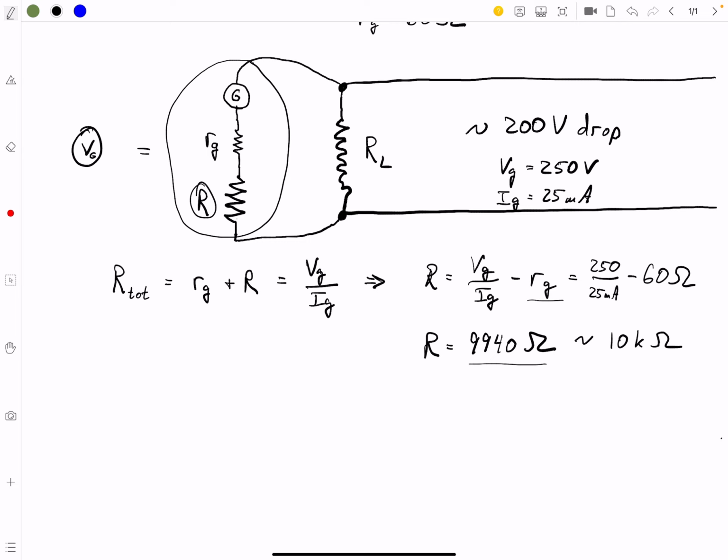So this is the resistance that we have to have in that, when we select that 250 milliamp selection, we are selecting this resistance inside as a shunt resistance. And all of that ends up giving us a 6.67 ohm shunt resistance. Okay? Good.